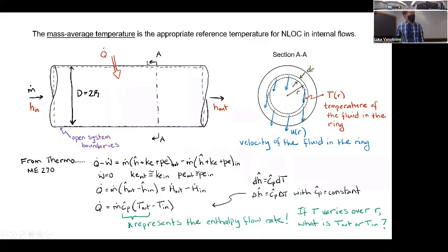And then, of course, we took advantage of the fact that there is this relationship between enthalpy and temperature, right? It's related through the specific heat at constant pressure, although for an incompressible liquid, constant pressure, constant volume doesn't really matter, right? C sub p is the same as C sub v, basically. And if we treat that specific heat to be constant, then this differential becomes a total change, right? And we can just represent changes in the enthalpy by C sub p times a change in temperature.